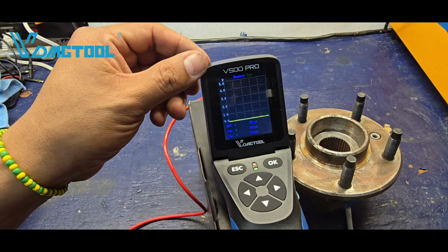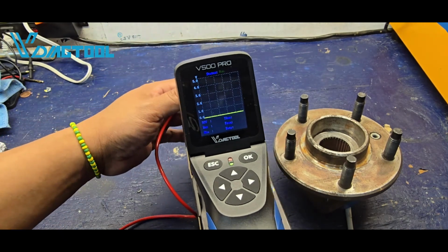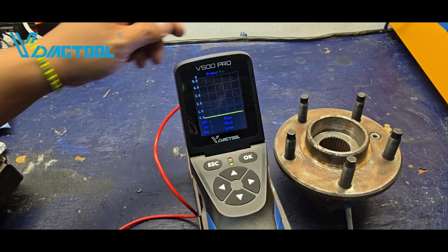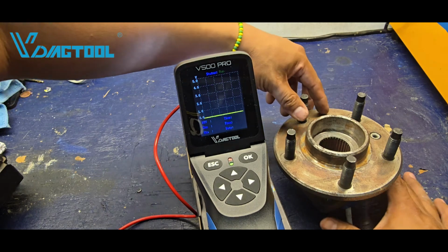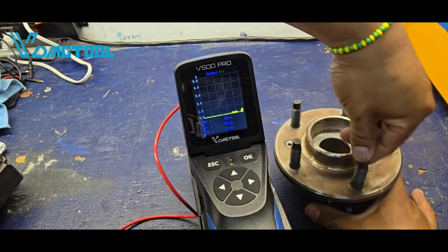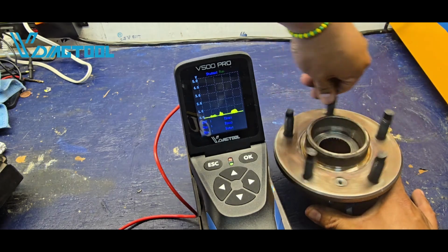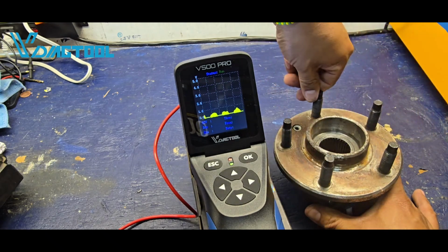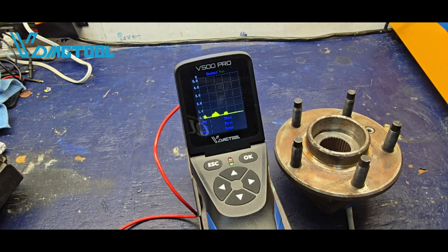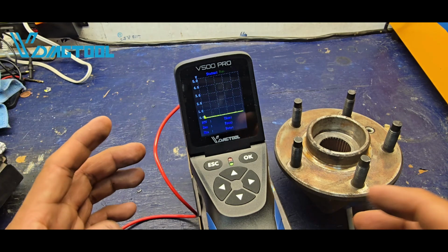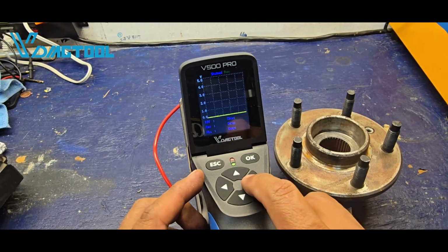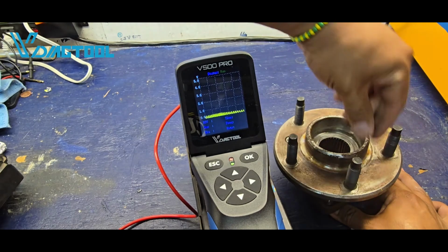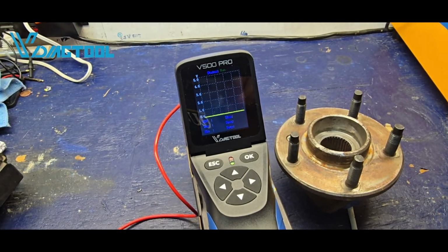We're going to set our tool right here on top. We have selected a 0 to 5 volt scale. The time frame sampling rate is 500 milliseconds. So we rotate this. You can see something changing on that screen, but not as good a waveform as you would like to see. That means our sampling rate of 500 milliseconds is too high. Let's scroll down to maybe 100 milliseconds. Let's try 100 milliseconds. As you can see, there is a difference on that waveform.